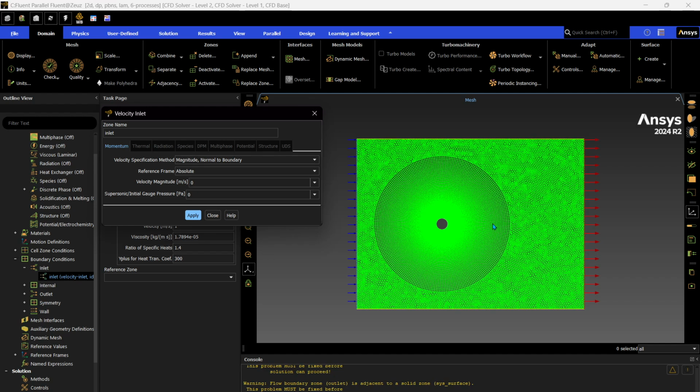I will be going with 150. Reynolds number is very low. This is just to make completely certain that it is truly laminar. So there we go. So 150, and to calculate velocity, it would be your Reynolds number times viscosity divided by your density times the diameter of the cylinder. So it's 150.